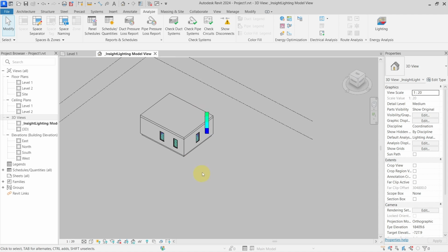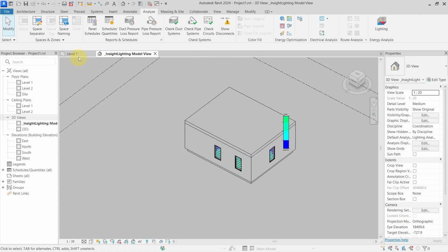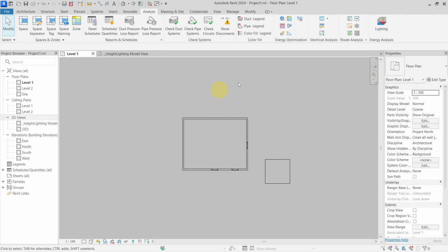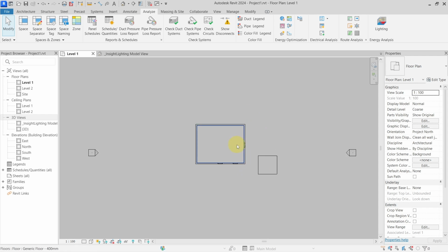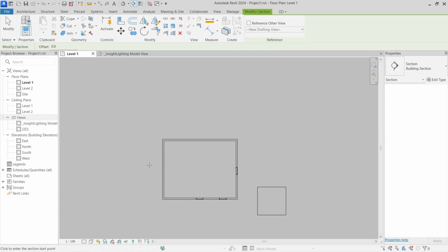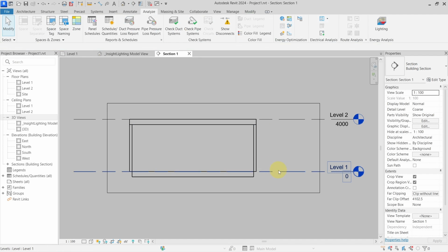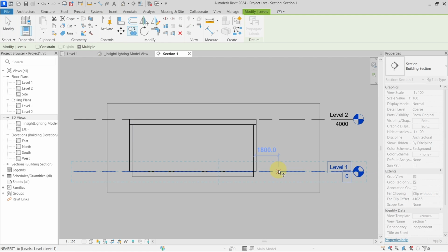Okay, then there is a next trick, how I can create a lighting analysis only on a portion. So let's imagine that I would have 4 floors here, or I don't know, 20 rooms, and I want to create analysis only in this room. So basically what I can do is to create a new level.